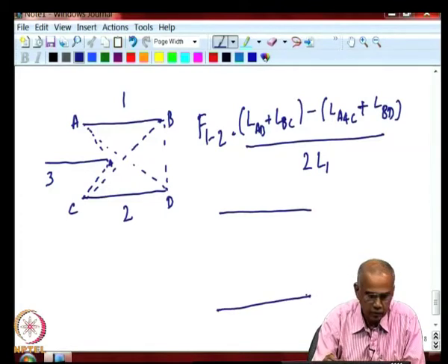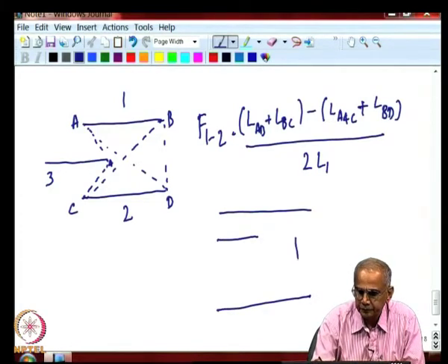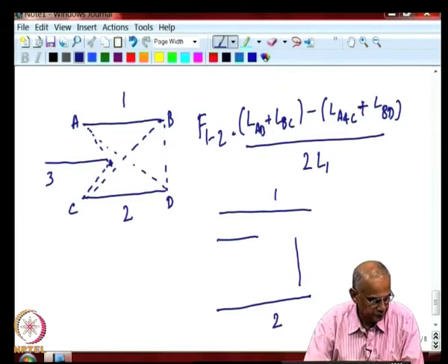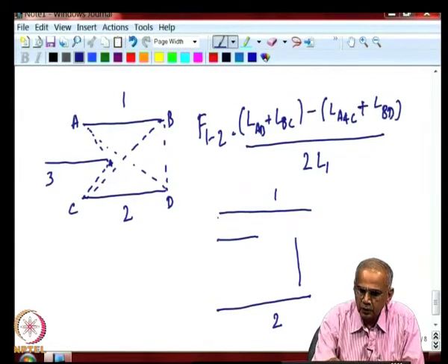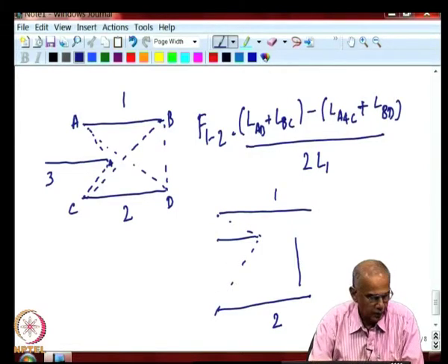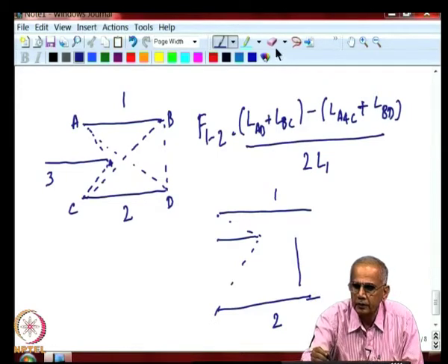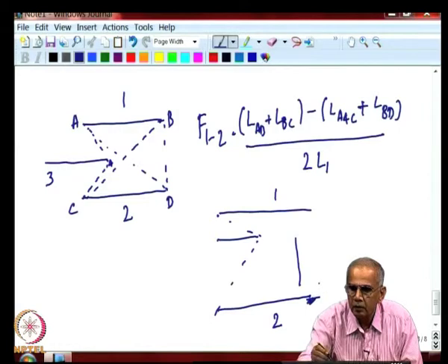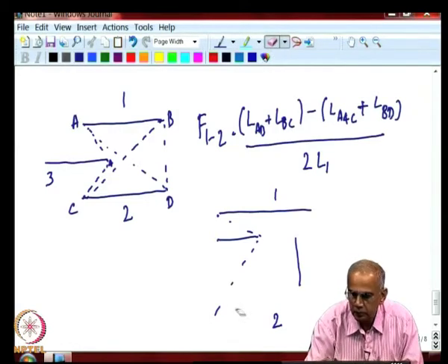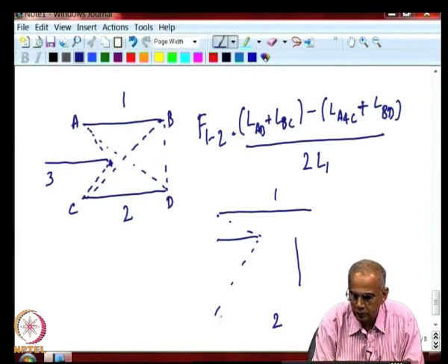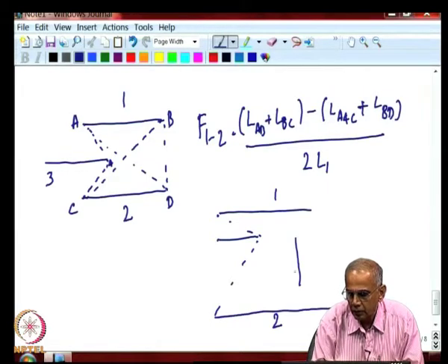Now, you have two obstructions. Okay. The surface 1, surface 2, there are 2 obstructions here. So, how do you draw the string? So, you have to of course draw the one parallel string same as before to keep the obstruction out. Then you have to draw the cross string here, like this and like this,